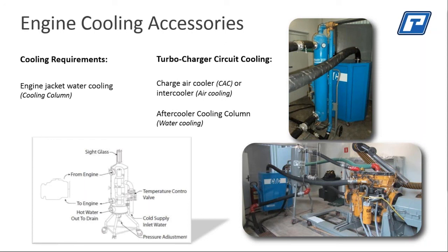Two systems are produced like this. I just went through the charge air cooler, or as they say internationally, that is typically called an intercooler. I noted on the slide that's air cooling. And the second method is called aftercooling. The aftercooling is doing the same thing. It's a method of cooling the turbocharged air prior to entry into the engine.